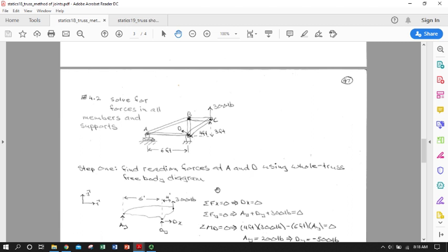Once you go into the joints themselves and you start looking at the pins, or if you have a space truss, probably a ball and socket representation, you're not going to be able to carry any moment in those joints, by definition of a truss. So all you'll have are the sum of the forces in the X and the Y, or X, Y, and Z. Solve them and generally work your way from one support to another, picking up the already solved force members at the subsequent joint to make your math easier. And remember that if you have a solvable truss, you'll have the same number of equations as unknowns. And even if you can't solve, if you have too many members coming into a particular pin, generally you'll be able to solve for that excess number of unknowns in the next pin over.